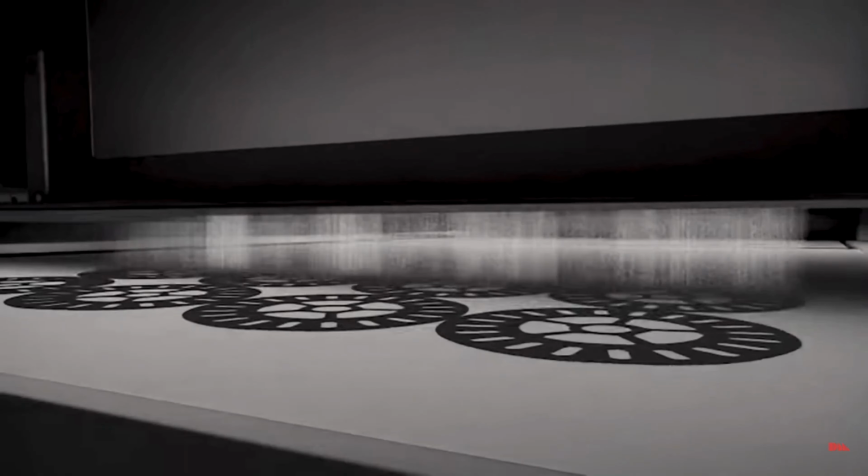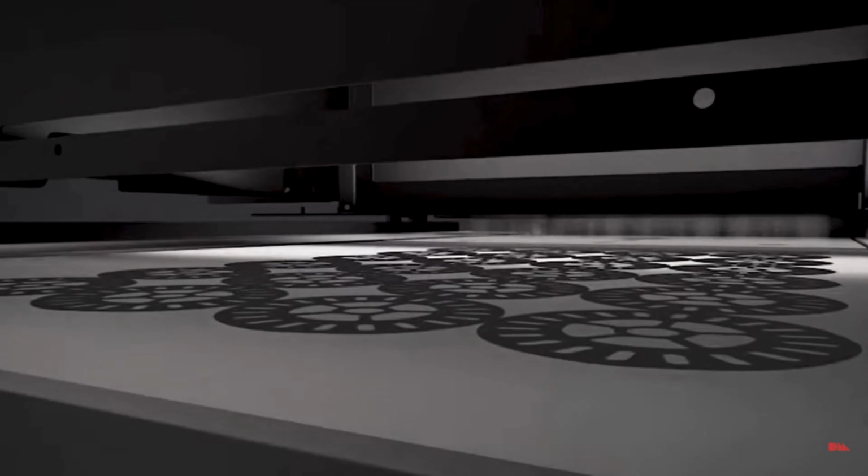Binder jetting is a 3D printing method used to make objects by putting a binding substance on a bed of powder material layer by layer. A special printer drops liquid binder onto a layer of powder following the shape of the object being made. The binder, usually a liquid glue, sticks the powder particles together where it is applied. This process is guided by digital design sliced into thin layers, controlling where the binder goes.